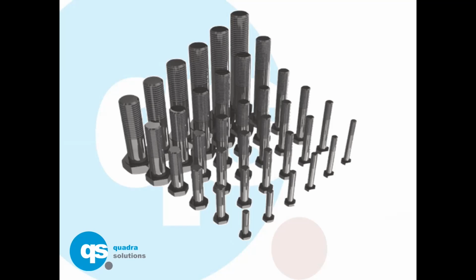Converting or creating this as a model state, I shouldn't say converting because you can't convert an iPart to a model state. There's no built-in mechanism. Creating a model state of this bolt, there would be one file on the hard drive. That one file can be large or small, long or fat or tall or thin, it doesn't matter. You can place 36 occurrences of that single IPT in your assembly, and each one can be set to a different size. You've still only got one file on the hard drive. So management-wise, I think it's going a long way.